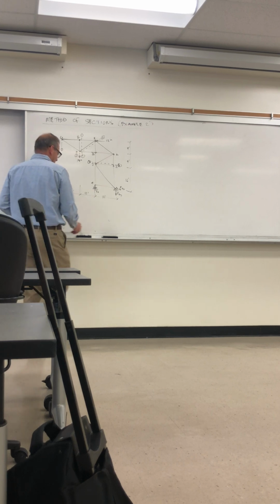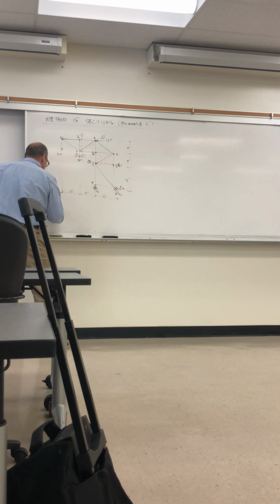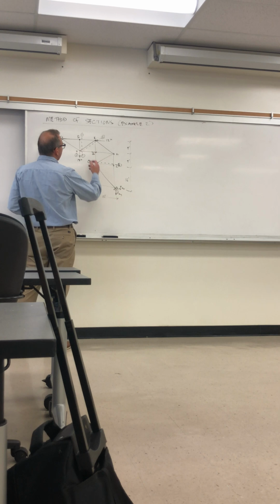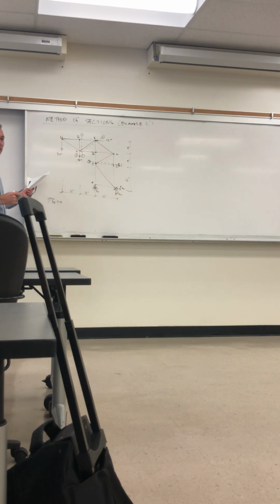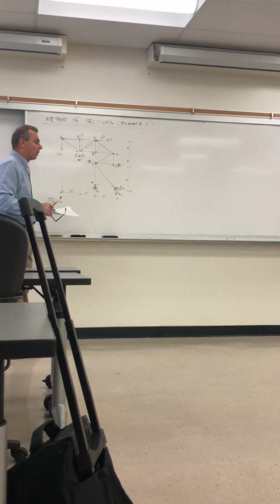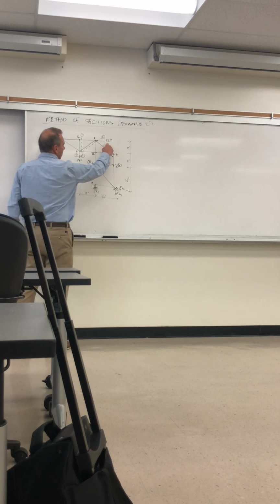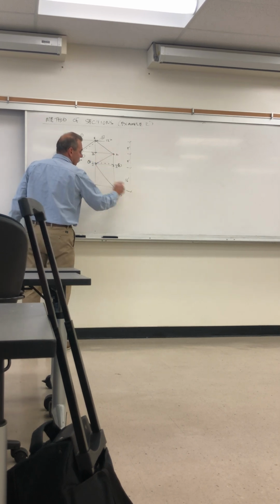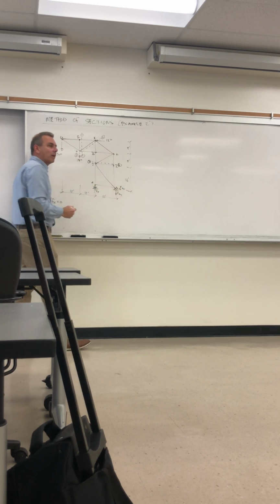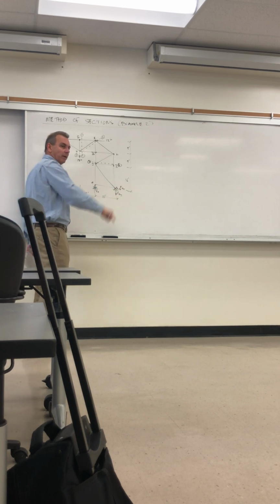So first we work with the reactions, of course. Summation of forces in x is 0. This is a roller. Any applied forces up above the reactions have to be taken out down at the reaction. There are no reactions up at the higher part of the structure. You can see there's a horizontal force applied there, so in the reaction I've sketched it that way. I could sketch it the other way; it would just come out negative, which means it's still that way.